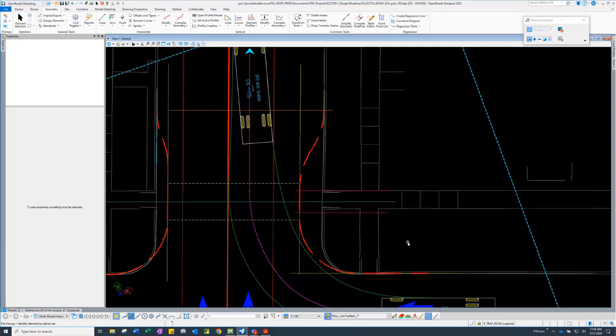Also have to remember, anytime you open a geometry file, then you open an annotation file or it will reprocess thinking you've done something even if you didn't. So right, it's to minimize the amount of reprocessing downstream for CAD as well. Oh, yeah, and it's the length of time that takes to open the file fully too, if you've got a lot of stuff in one file, as opposed to attached by a reference. Yeah, that's a good question though.